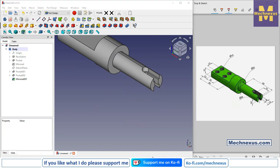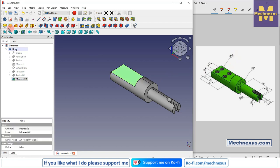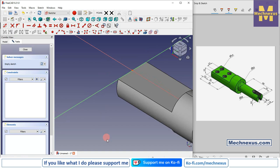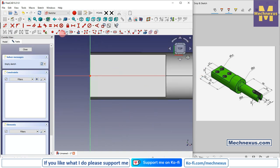Now we will move to the next feature, which is to create these 4 holes. So we can make this hole with a hole wizard tool, but it is a simple hole of dia 14, so I will make it with a sketch. So I will select the face and click on the sketch, and I switch to the isometric. So first thing I will switch to the right orientation,